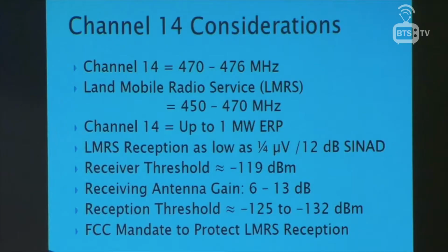So let me continue on now and start looking at channel 14. Turns out that many of the issues that come up when we're talking about the mask filters for stations elsewhere than channel 14 apply as well on channel 14. But we have even more considerations here. To start with, for the baseline, channel 14, as a reminder, is 470 to 476 megahertz. The land mobile service goes from 450 to 470 megahertz.